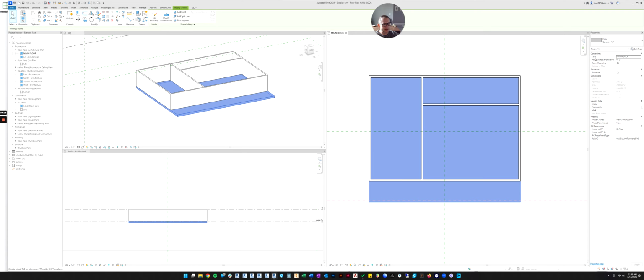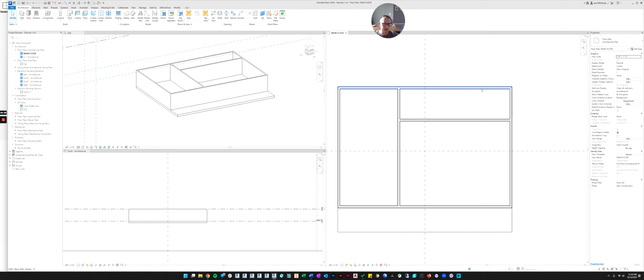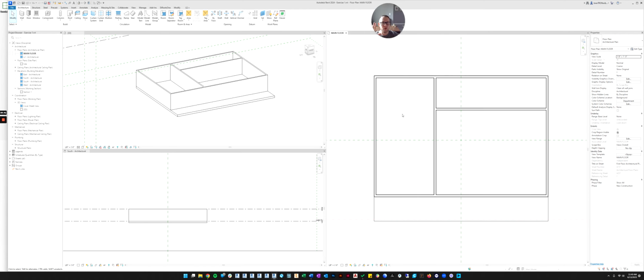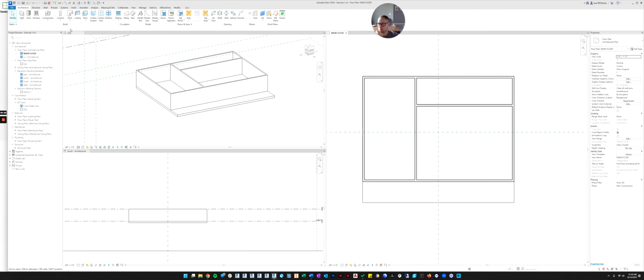So it automatically associated the floor with the main floor plan, with the main level. Now as we do the ceilings, it's going to do the same thing. If I'm in level 1, it's going to assume you want to draw the ceiling on level 1, but that's not what we want. Or maybe it is, but then we'll need to push it off. If we draw ceilings right now, it's going to draw them on the floor. Let's maybe just do that so that you can see.